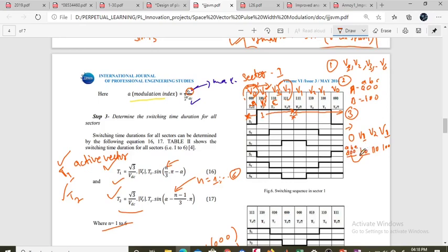So that means only a phase will be shifting from positive to negative, that means it is valid. Now just check here, for 1 0 0, 1 is already here, 0 is already here, 1 is already here in A and C, only the B phase transits, right, only one B phase transits. Then this sequence is okay, is good.